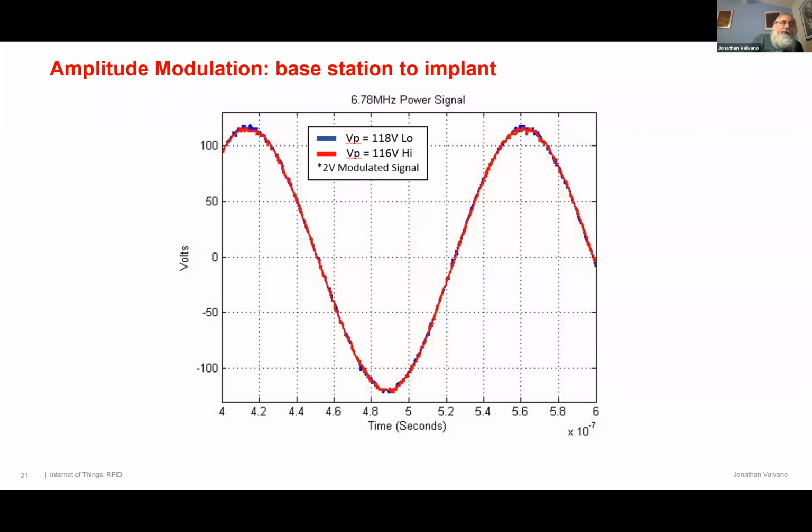All right, so how about I'll do an easy one? How do you make a 6 megahertz square wave? Crystal oscillator. Yeah, a crystal oscillator. And how do you make a square wave into a sine wave? Well, with a filter. Remove the harmonics, okay.